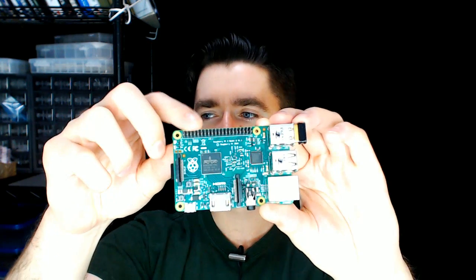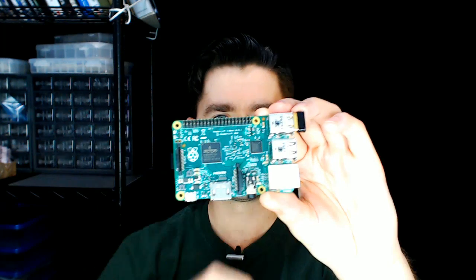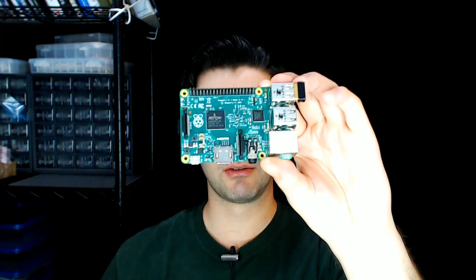We're going to build something onto the leftmost 10 pins of a Raspberry Pi, but it's going to be a very simple thing. There's going to be two LEDs, one of which goes on whenever you plug it in, so it's powered, and the other one that turns on when you turn it on. From here, you'll make a small board that you can practice SMT soldering on, which is not as scary as you think it is. You can also practice doing some GPIO output. From there, you can use this as a launching pad for building your next thing.